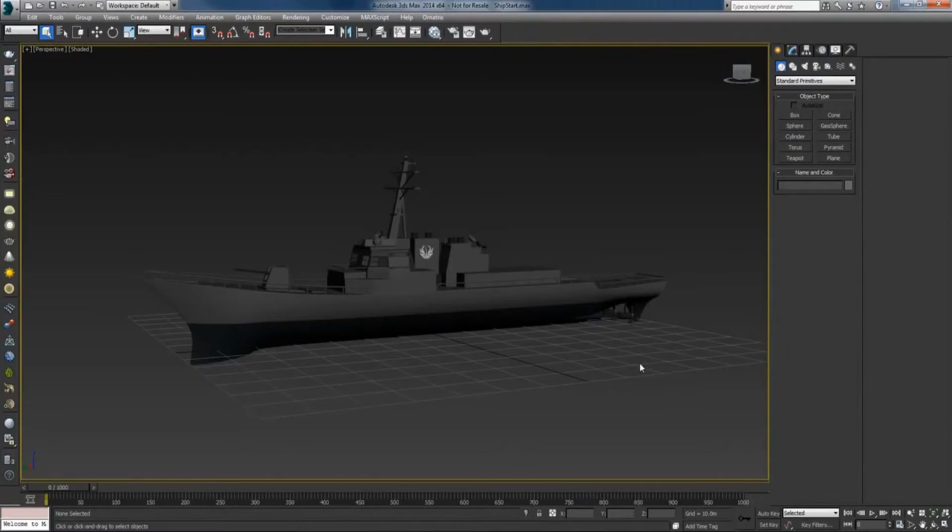And it's easy for me to work with meters, but if you're located in, let's say, UK, you're probably used to the imperial units, and in such case it will be easier to work with feet instead of meters. So what's important to remember is that not the units, but the size of the object is what matters when you do simulations. So if you have a ship that is 150 meters long, that's correct. And if you have a ship that is 430 feet long, that's correct also.